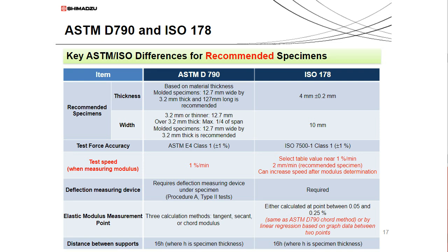For a bending test, the dimensions of the sample, such as thickness, width, and span, matter greatly because they will result in different effective strains and stresses on the sample, and also determine what crosshead displacement is required for a specific strain rate.